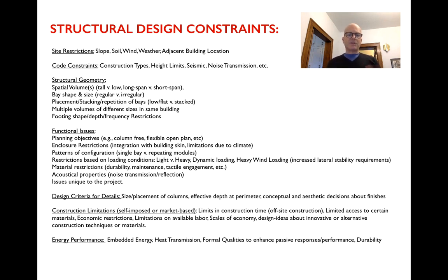And then we'll get into the architectural considerations. So does our client want tall spaces or low spaces, long span, short span, multi-story or single story? What are the patterns of use and how do those relate to the way that a structural grid might develop? Are the bays repetitive? Are there places where we can put in systems that will allow for greater lateral stability, and how do we integrate those very solid pieces with our client's need for maybe some more open spaces?